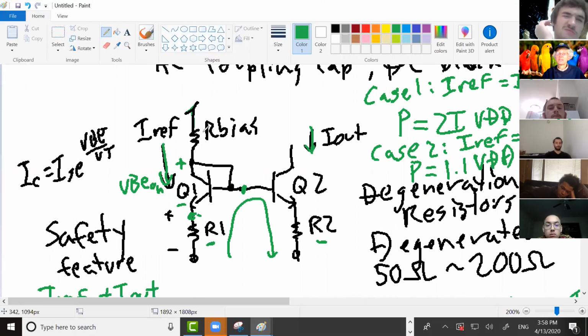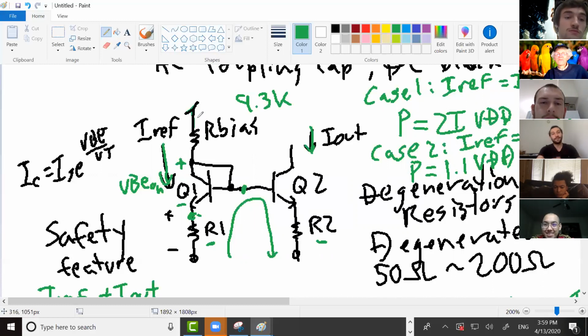And if you have the same current, let's say you got 9.3K for your original R bias. And then you made R1 100 ohms. What would you have to do to R bias to get the same voltage? Oh, I'm killing this question. How do you get the same current?